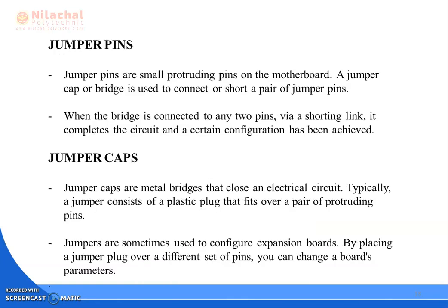Next we will be discussing jumper pins and jumper caps. Both are used for the plug-in and plug-off concept, so that one can complete an electrical circuit for the power supply. Jumper pins are small projecting pins on the motherboard. A jumper cap or bridge is used to connect a pair of jumper pins. When the bridge is connected to any two pins via a shorting link, it completes the circuit and a certain configuration is activated, and we get the output.